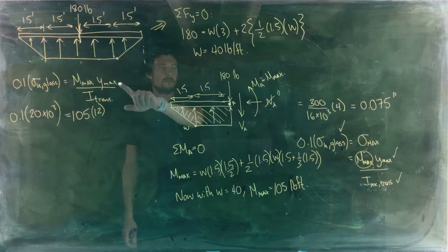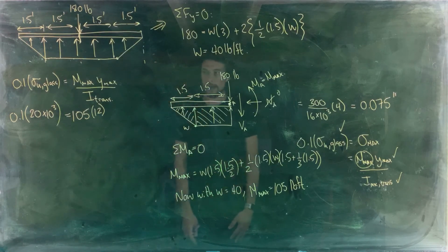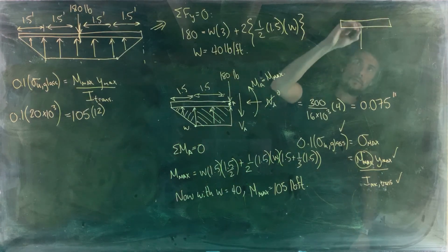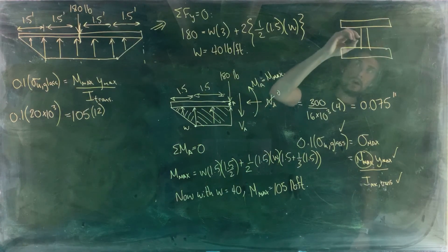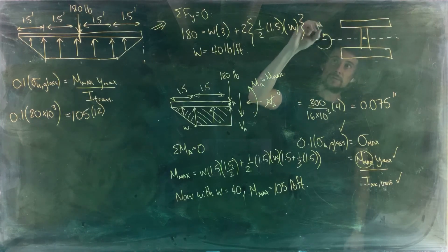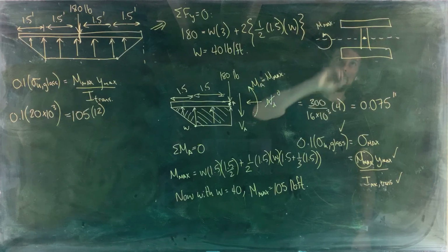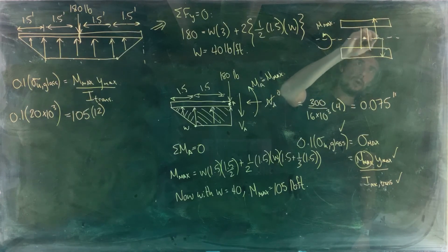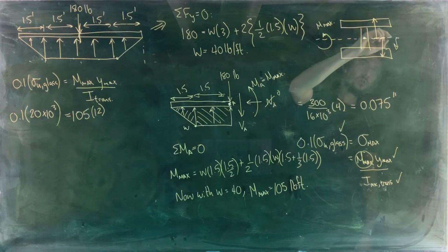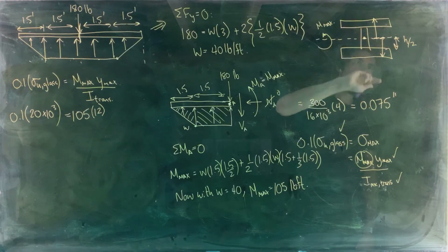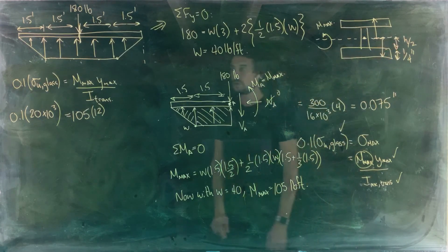Then our maximum value of y, again here in our transformed beam, we are having a maximum moment that's occurring about a horizontal centroidal axis. So the farthest we can go is all the way to the top or all the way to the bottom of the cross section, which in either case is our unknown height of the foam divided by 2 plus an extra 1/4 inch.